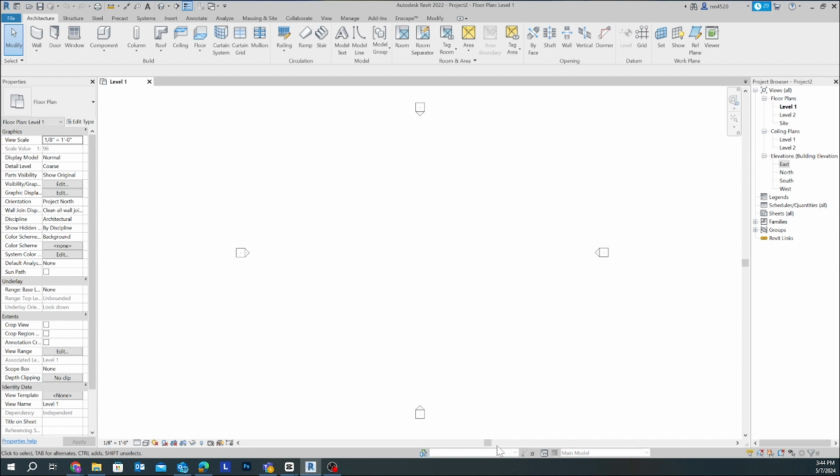Now coming towards the bottom line, what we have over here is the scale. Very important, because in most of your projects they actually ask you to use 1/4" scale, or at times they can ask you 1/8" scale or 1/32" scale. So you need to make plans according to that. Right now what I am personally using is 1/8" scale, that is equal to 1 foot. So the scale for architecture students or civil students is something very important. So you need to get familiar with this as well.